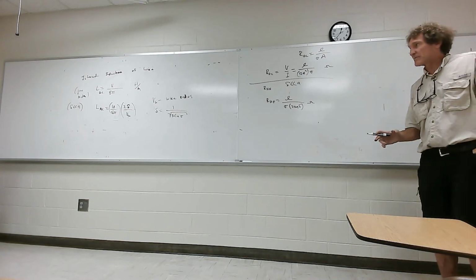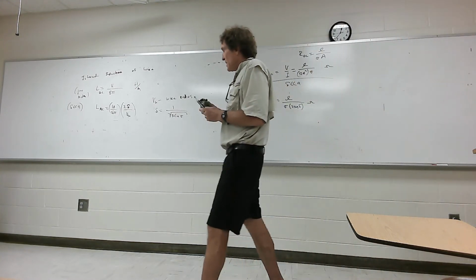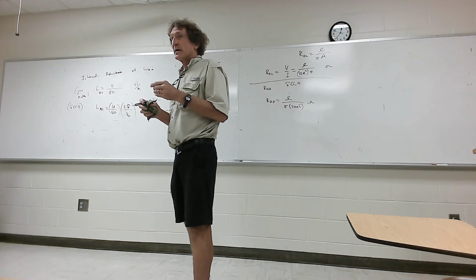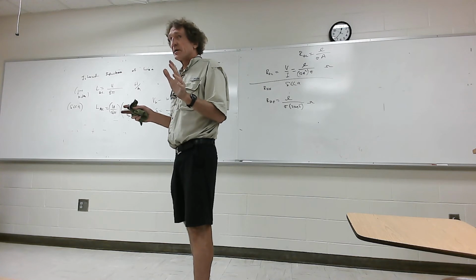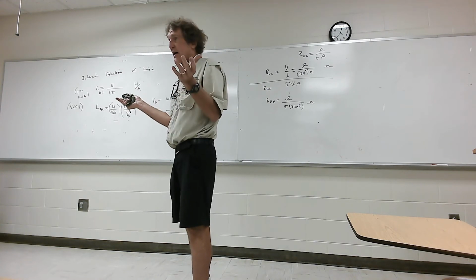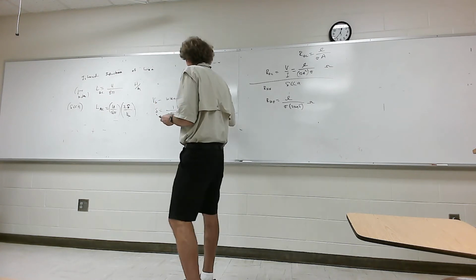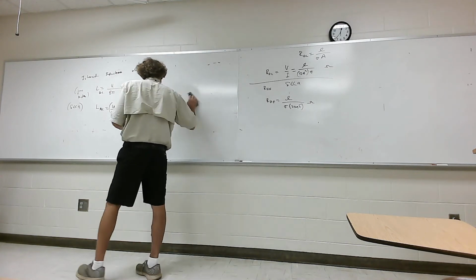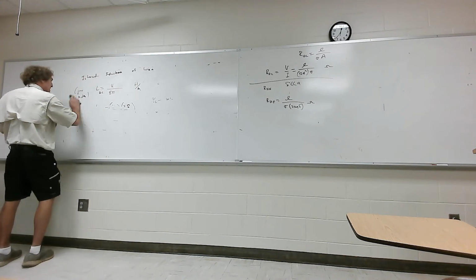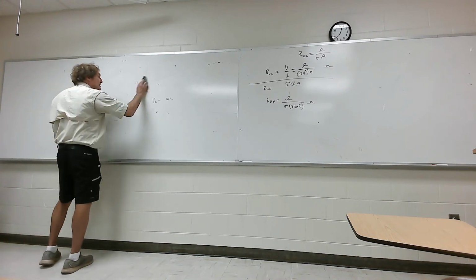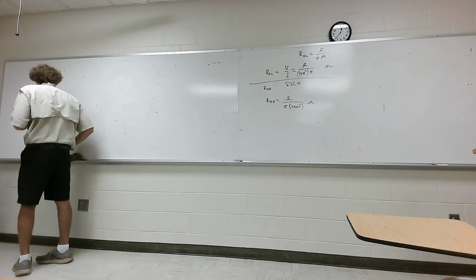Now, the next thing you have to be aware of, internal inductance may or may not be important, because the dominant inductance usually has to do with magnetic energy outside that wire. That's usually the thing that limits everything. So now you have to talk about the return path for current. And this is important that you appreciate this.